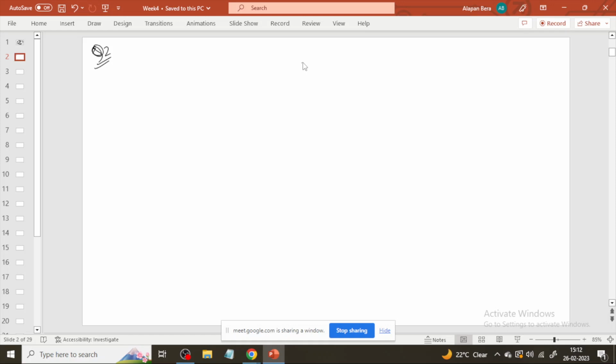This is the normal metal region. In the case of a Josephson junction, this has to be sandwiched between two superconductors, so there should be one superconductor on the left and one on the right. This normal metal region is very thin, on the order of nanometers, or on the order of the coherence length of these superconductor pairs.